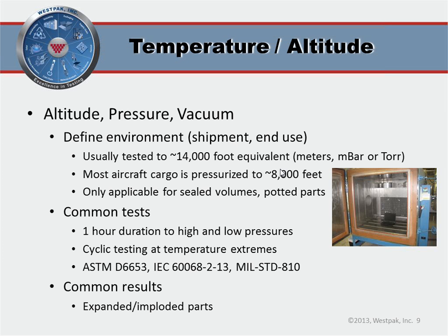Sometimes we'll do cyclic pressure testing at temperature extremes, just trying to mechanically stress parts. Common results are expanded and imploded parts. Oftentimes people think about venting the pressure when you go up in elevation, but they don't think about letting the air go back in when you come back down.